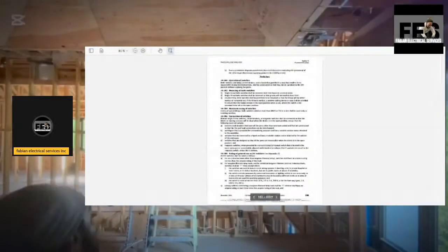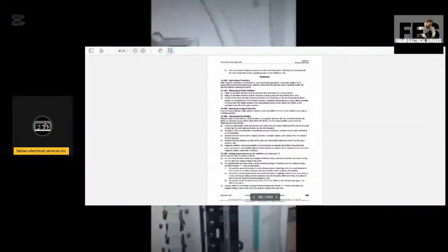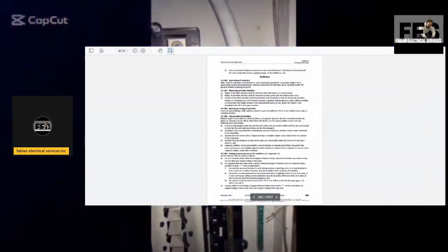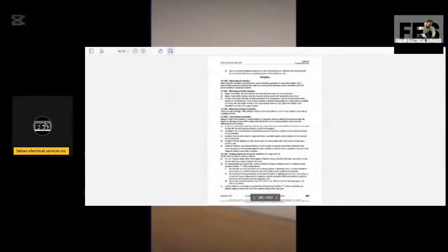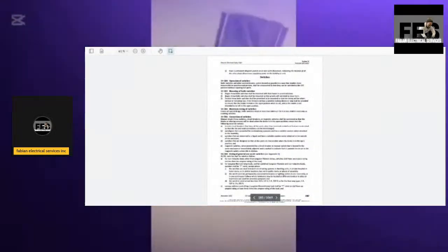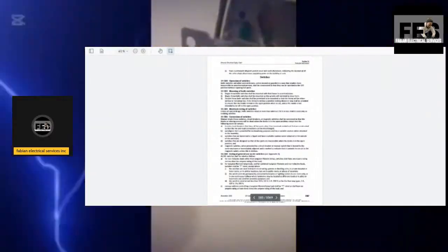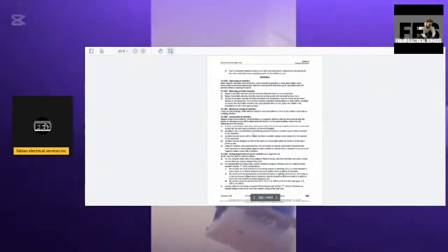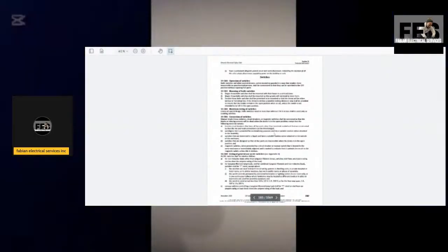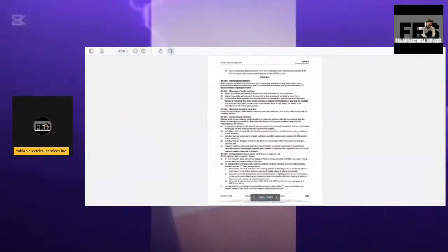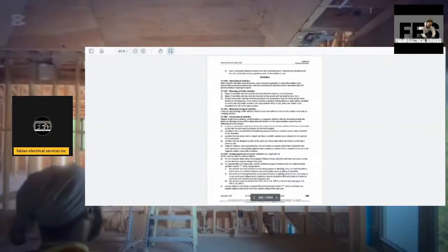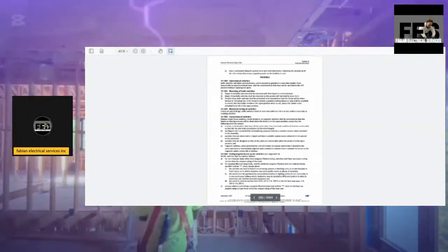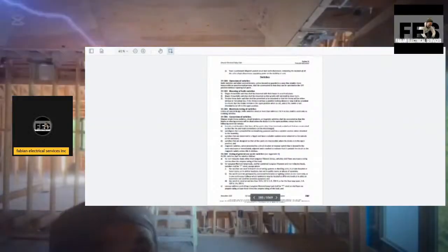It goes on to say: branch circuits that have all live parts other than terminal seals and that are constructed so that the line and load connection can be interchanged. Switchgear that is provided for sectional purposes and has a suitable caution notice attached to the assembly. So the switchgear, you normally find that in commercial buildings inside of the main electrical room.